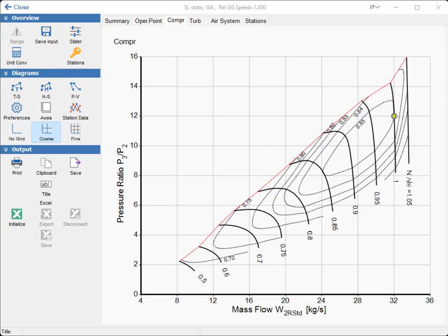This compressor map is the standard map included in GasTurb. It is scaled according to our chosen input data, such that the scaling reference point of the map corresponds to the cycle design point. In many cases, the standard map yields reasonable trends. In other cases, depending on the machine type and design, for example, if a centrifugal compressor is used, a different map should be used to accurately predict operating behavior. Let us now look at how to select a different map.